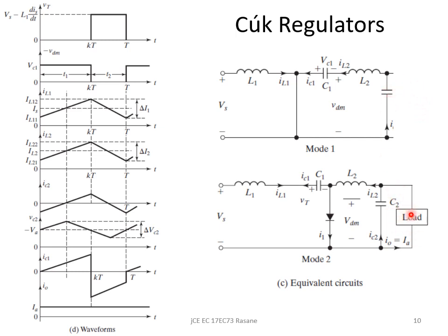So this load is going to have the same voltage, and since the load is filtered, only DC is going to come here. The DC value of the load is VA. That's how I call it, and in our Cuk case, it is inverted with respect to the input, so we write it as minus VA, and I get a rippling effect across the capacitor. So that is your delta VC2, that is the filtering effect.